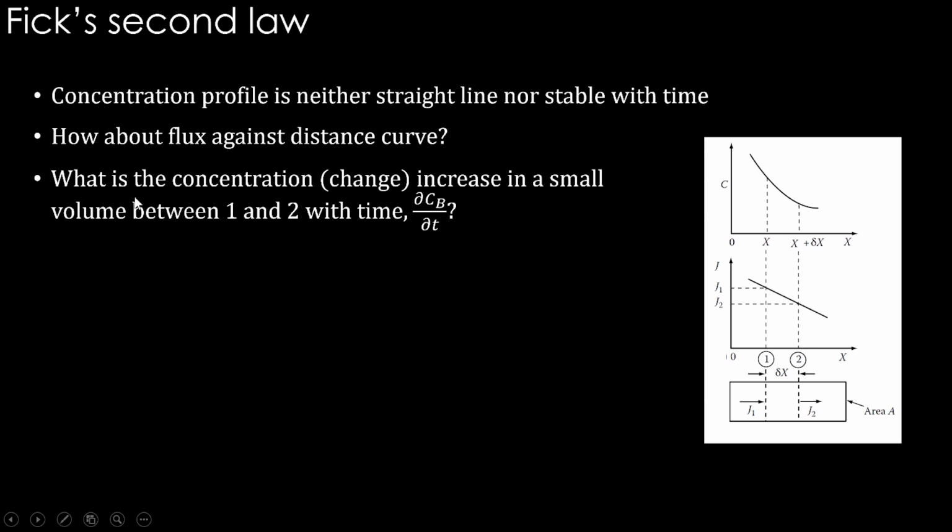Therefore, this question comes: what is the concentration change or concentration increase in a small volume between 1 and 2 with time? Meaning, what is the concentration increase over time? This question is important when it comes to this kind of non-steady state diffusion. Somewhere the concentration is going to increase or decrease. What is the change in concentration over time?